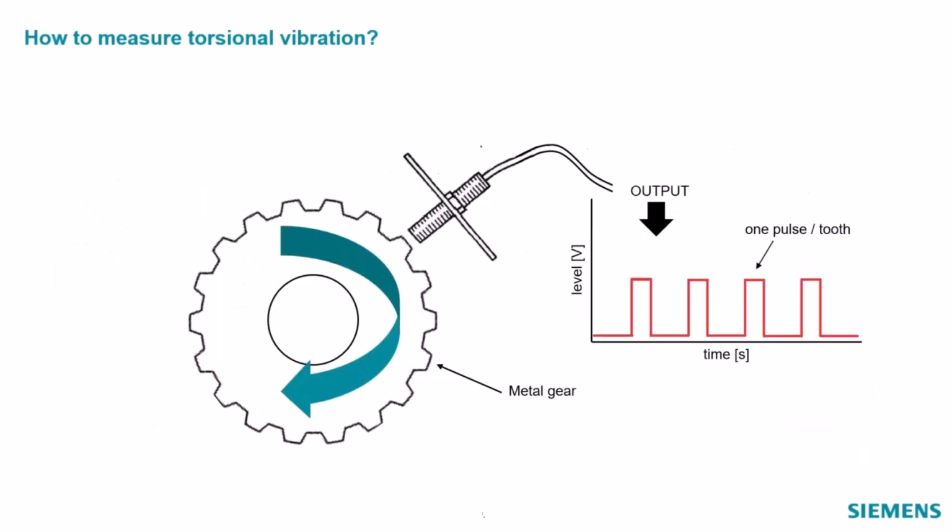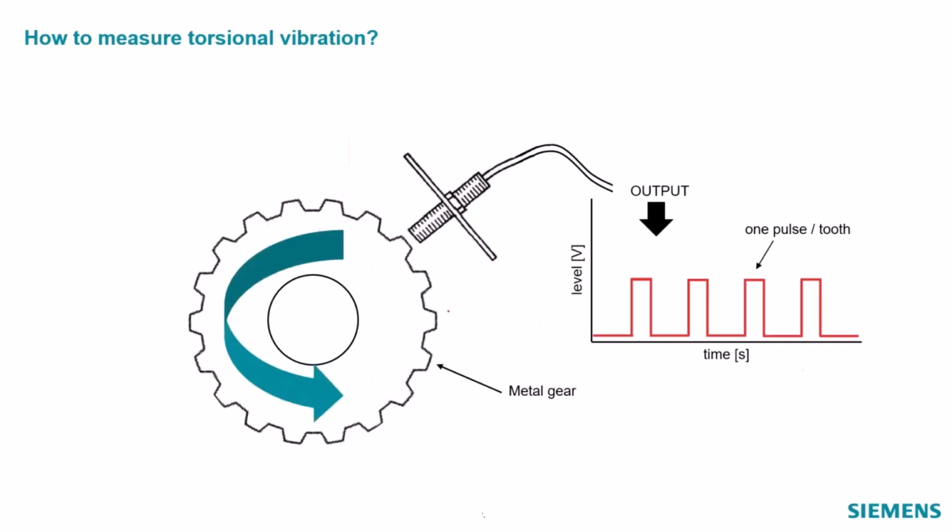Now, let's say I've got a gear rotating this way. See that? Like 4 or 5 teeth went by, so I see these pulses. And then my gear spins the other way, same amount. Would this signal look any different? No, it wouldn't. So with all these things that I just presented, if the system was going forward or backward, you would not be able to know. The number of pulses is the same regardless of the direction.